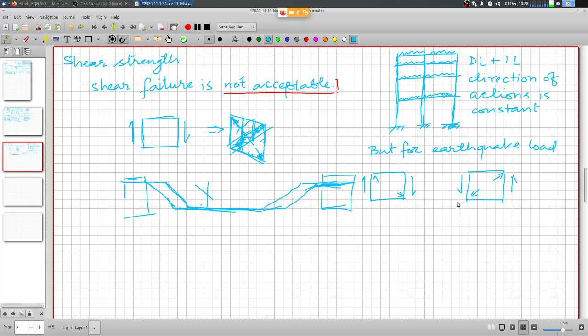So in this situation, this kind of bent up bar schedule is not really helpful. Therefore the bent up bar is not advisable for developing shear capacity in the section for earthquake resistance, and we need to go for only vertical stirrups.